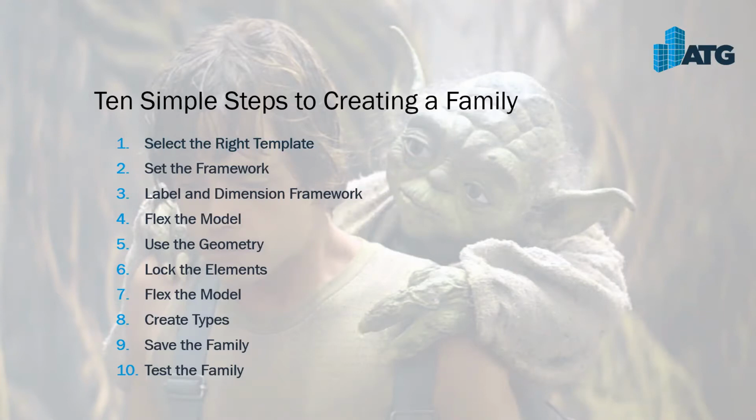As I do this, I go in and flex the model. That means I'm testing out, changing information in the labels to see if reference planes are adjusting as expected. And then I go in and start adding the geometry. So I showed some different options with the geometry. And then I locked that geometry to the reference planes, and then flexed the model again. So again, I tested to make sure that the geometry was moving with the reference planes that were created.